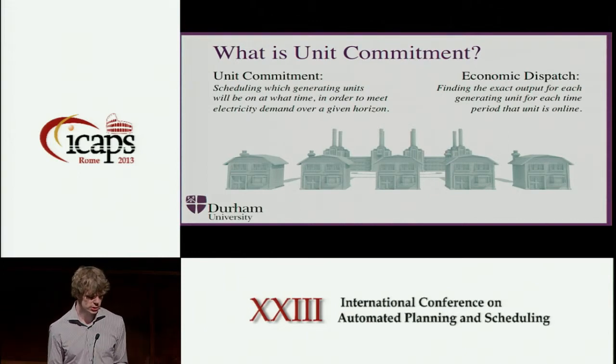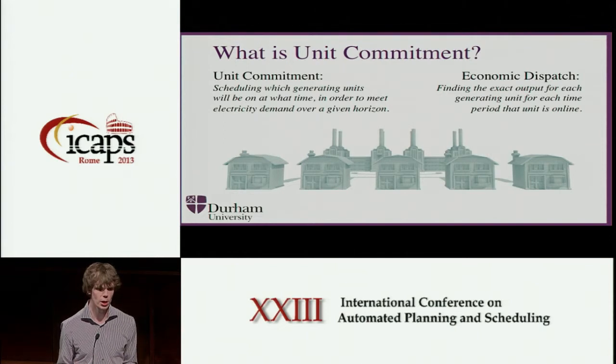Now, even though dispatch is calculated for the full planning horizon as part of unit commitment, in reality, the actual outputs of generating units are not set by their final unit commitment schedule, but by more complex economic dispatch algorithms run closer to real time. This means that the key part of a unit commitment solution is not the outputs of a generating unit, but the temporal online-offline schedules produced for each unit.